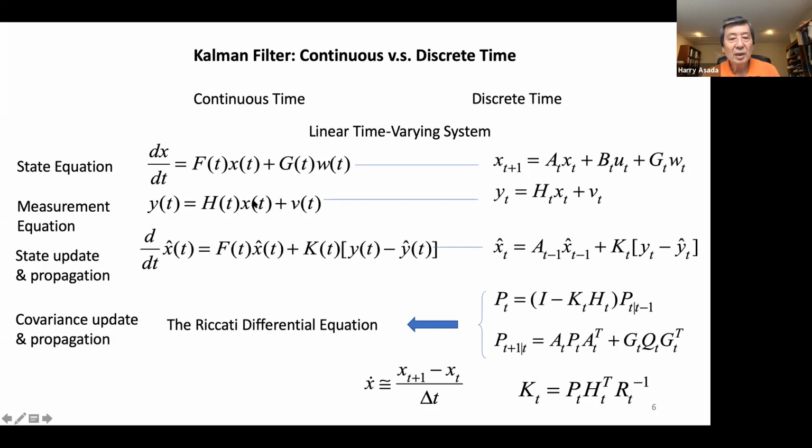So here too, we just cut and paste this part, and right here, this is similar to these equations, and then we just propagate XT with this FT. In addition, we have this correction to the state, okay? Now, in the case of the discrete time Kalman filter, we had two formulas for covariance update and covariance propagation.